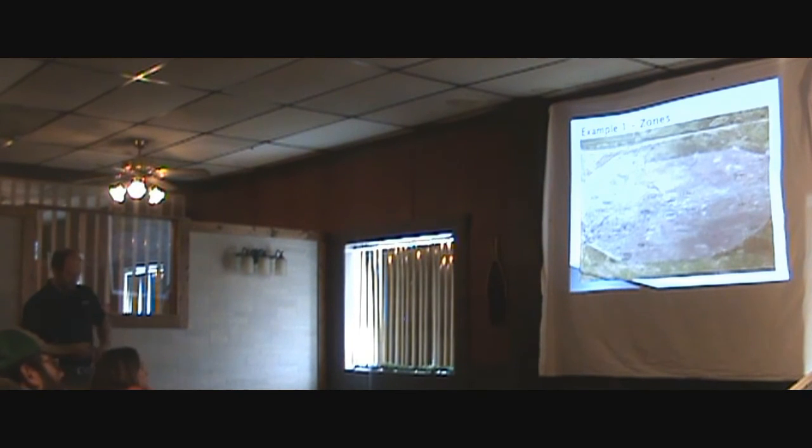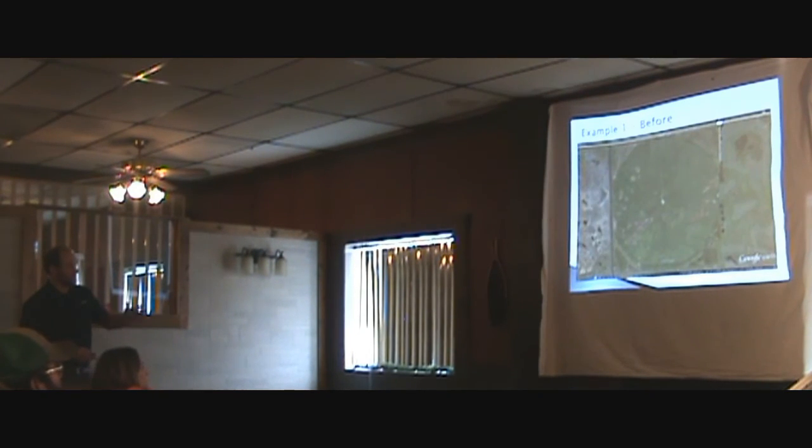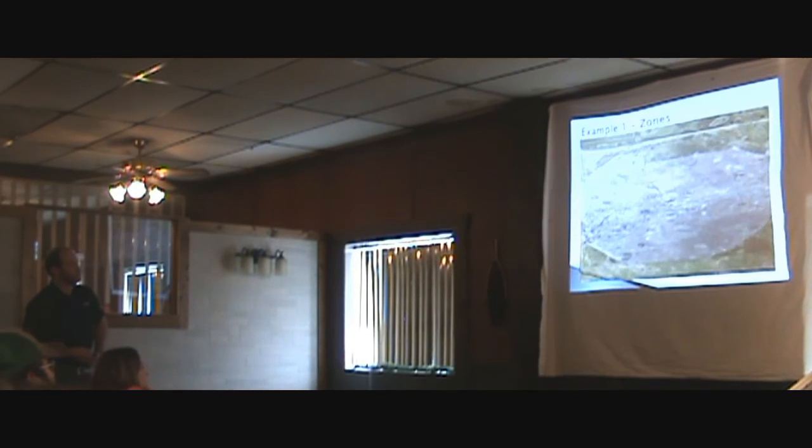So what we did was, this was the plan we put up, broke it up into some zones which are pretty much the same as the zones we looked at here. We applied it that way. In this particular example, it had two pumps, one here, one here. These had the flat curve like we talked about. This system was nozzled for 800. When we took it down to 400, the pressure only went up about 10 pounds. So this was one of the cases where we didn't have to change it, didn't quite need the VFD for it, and ran it that way.